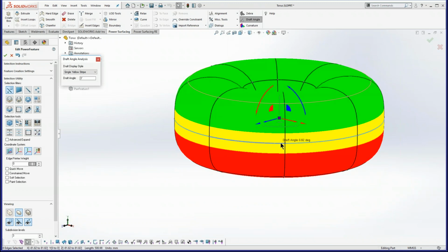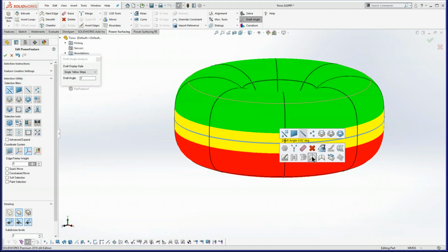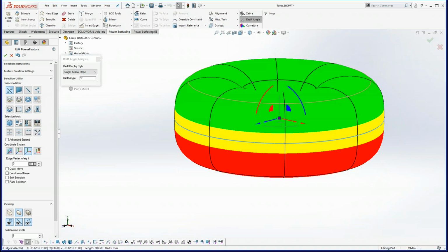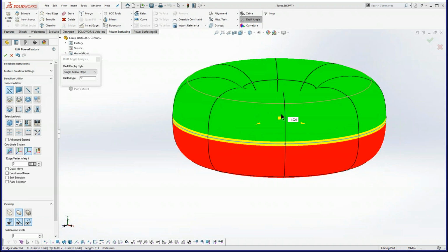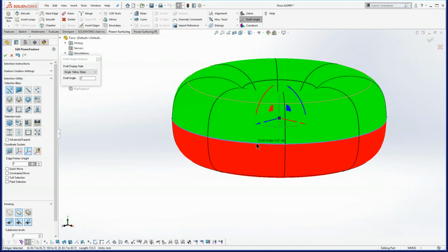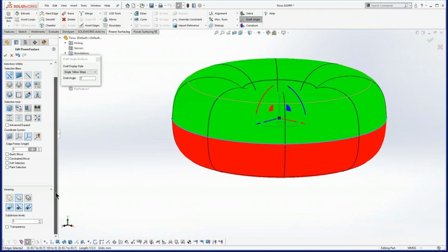Usually you would set your edge to hard edge. It's not going to make any difference on this one because it's fairly flat here. But if I now scale this selected edge out, you can see that my area gets smaller and smaller. And right about there, if I hover, I now have 3.87, so it's still maybe a teeny bit big. You can sometimes increase the viewport subdivisions level, and that'll help you out.